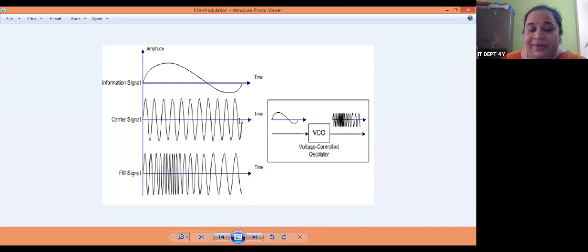The same amplitude levels and time span can be decoded in the demodulation procedure of the FM demodulator at your receiver side or receiver device. The particular frequency levels will be detected, and according to the frequency levels detected, the amplitude level of the modulating signal will be recovered in the FM demodulator of your mobile or whatever communication device. This is the frequency modulation, right?